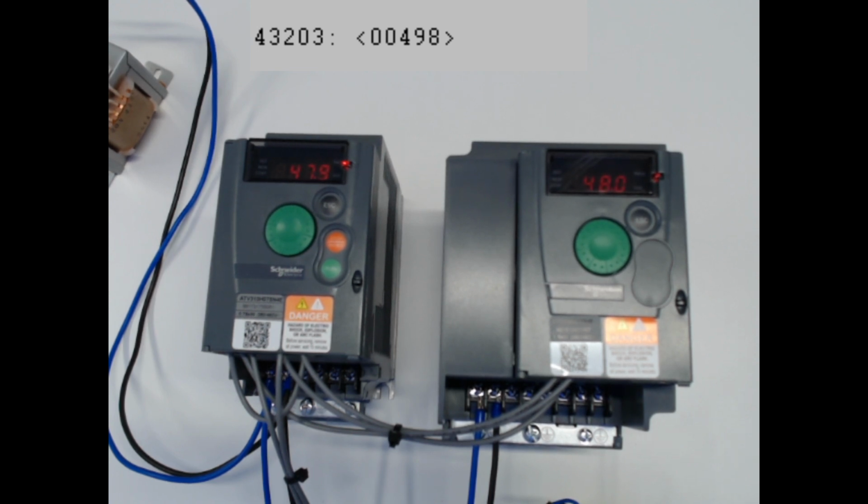So I'm going to show you how it destages. If you want to make the pump destage, now we have to increase the sensor value to the set point, which is more than what we set. Right now it's at 0.01 bar more than the set point. So you can see that now both the drives are starting to ramp down. It's at 42, 43 and going down. So I'm going to speed it up a little bit faster.